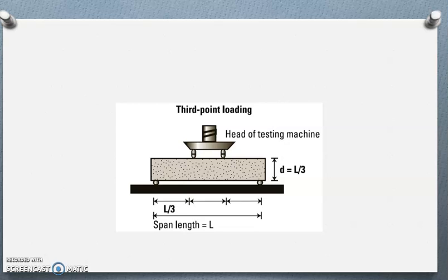Okay, we have to prepare it using the tamping bar which weighs around 2 kg. By layer you will be filling it. In the flexural testing machine, we have to place that beam after it has cured. The bed of the testing machine shall be provided with 2 steel rollers, this round and this round. There are 2 steel rollers which are 38 mm in diameter, on which the specimen is supported.